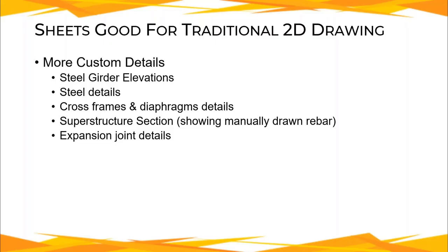Finger joints, but you can model the gap for, let's say, a strip seal or a poured joint with backer rod. That's just the gap, and then you have backer rod and stuff in there. Strip seal, you have the steel components in there, but that kind of stuff.